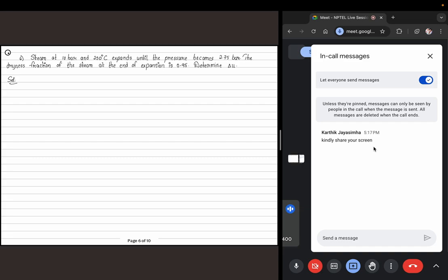As you see the pattern, all of these questions will deal more or less with this: you just identify the initial state, final state, and then you calculate delta U based on the difference between them. The main step is how do you calculate the properties. Up until now we have been using steam tables. So you just look up the table, take some linear interpolation and get the value appropriately.